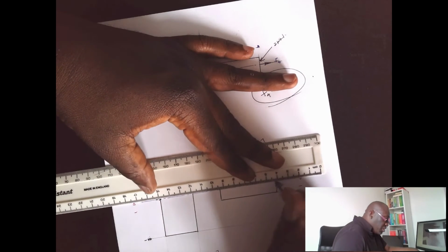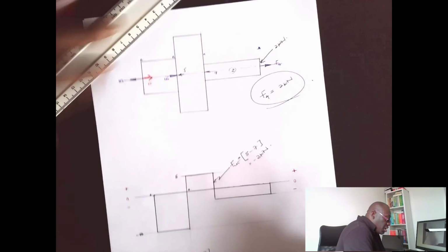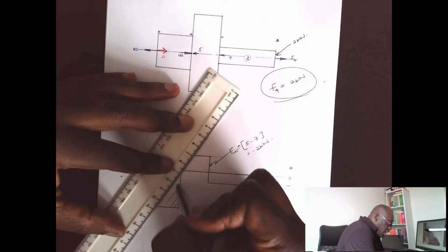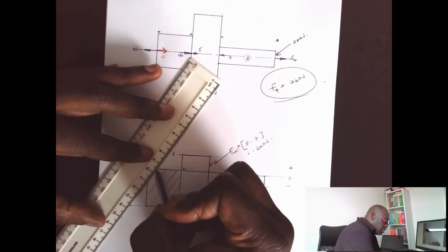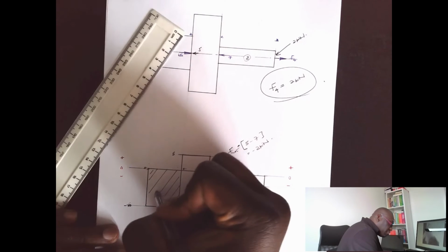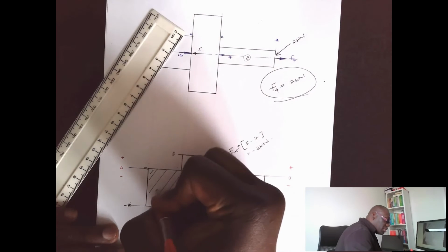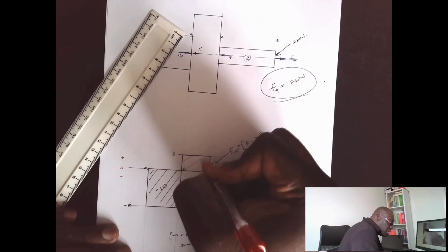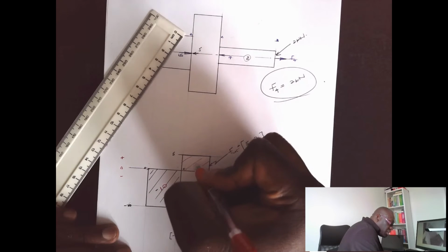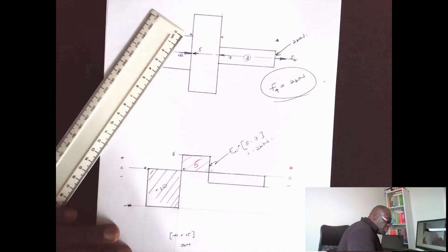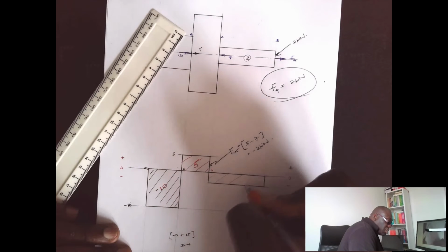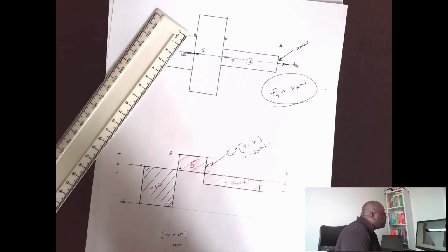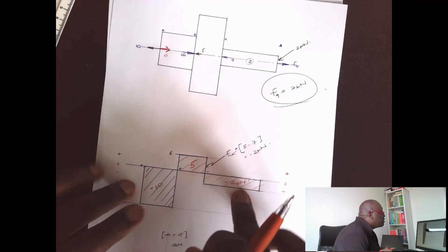And this, ladies and gentlemen, gives us the force diagram, or the load diagram. Okay. So for section AB, this is minus 10. Let's use the red pen. This will be minus 10 kilonewtons. For section BC, that will be 5 kilonewtons. And for section CD, that will be minus 2 kilonewtons. And these are the internal forces in the material.